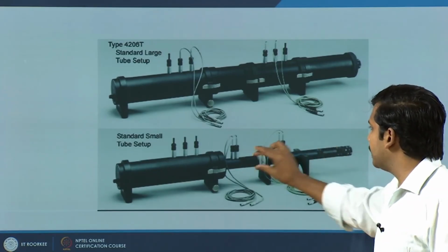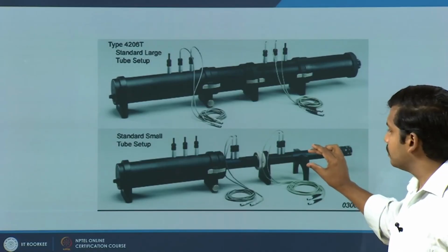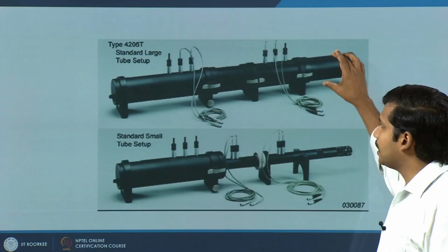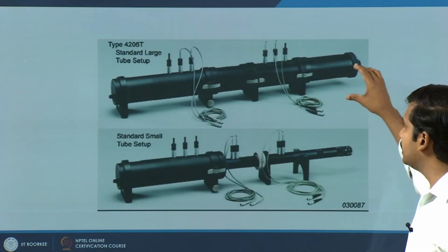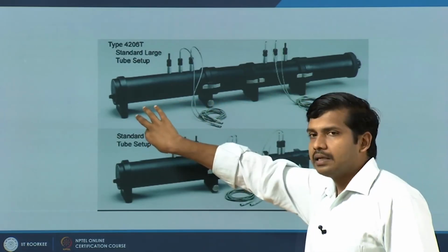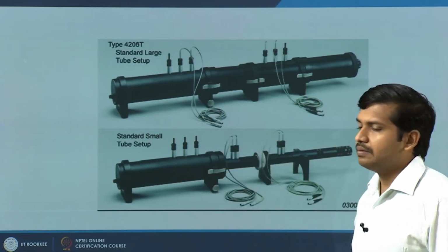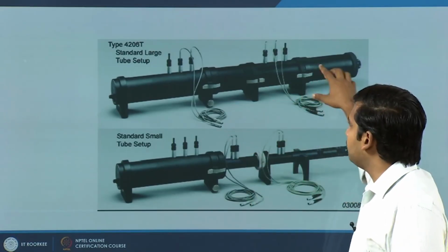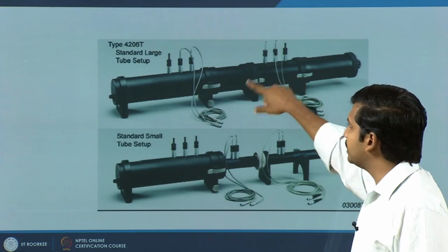Say this kind of thinner tubes, thin diameter, smaller radius tubes are used for high frequency testing, the larger ones used for typically low frequency testing. On one side of it you mount the material, there is a signal generator or a pure tone generator, and a specific frequency is set in which tones are produced.